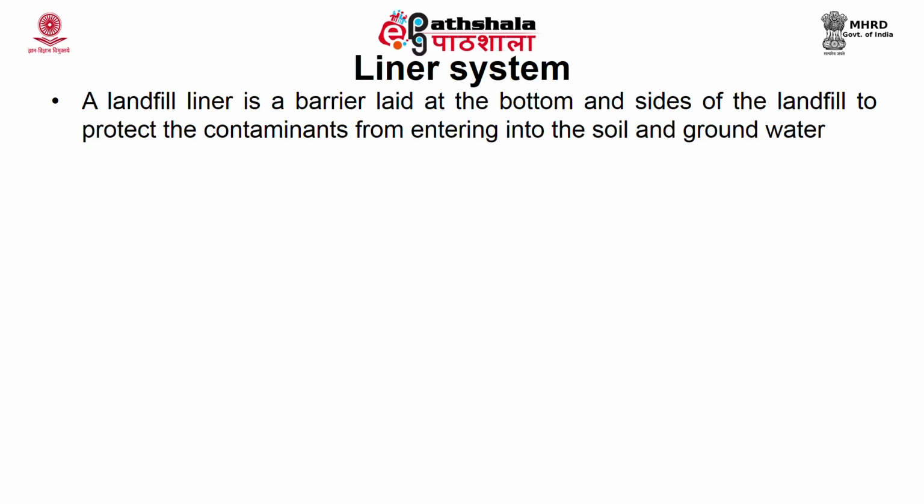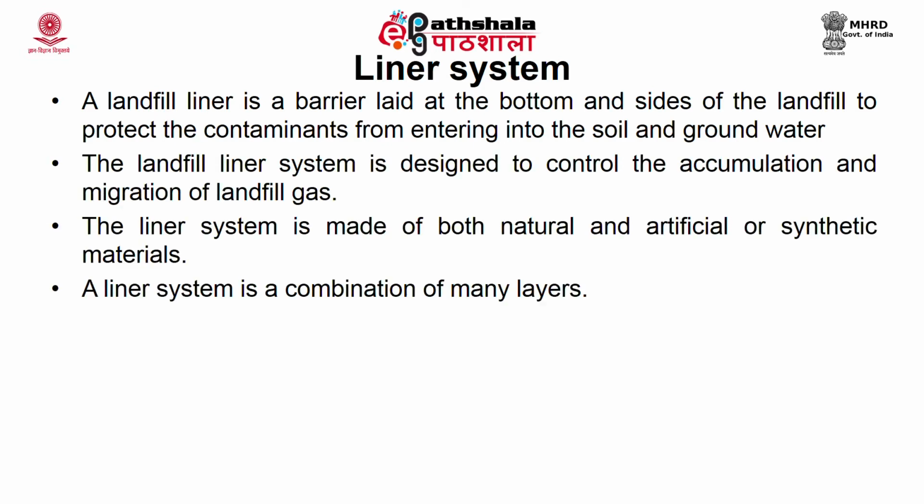Now, let us look into the first component of the landfill, which is the liner system. A landfill liner is a barrier laid at the bottom and at the sides of the landfill, so that the environment is protected against the contaminants and their entry into the soil and groundwater. The landfill liner system is designed to control the accumulation and migration of landfill gas. It is again made up of both natural as well as artificial or synthetic material.